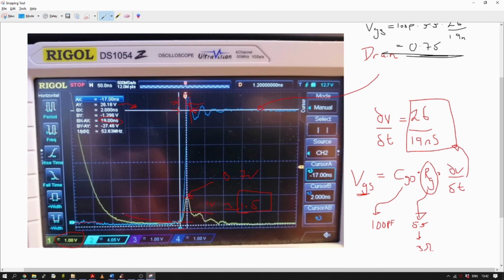things. You can see here that this is a turn-off curve. It's quite nice and smooth. There's no ringing, which is going to induce any nasty EMI. So I could probably drop it down a bit to 3 ohms, and that would drop this down sufficiently that I'm not turning on the FET. But as you can see, there isn't any evidence of shoot-through. If there was, you'd see this blue line doing some horrible stuff, and these FETs would be heating up considerably, but I'm not seeing any of that. But it is something that maybe I want to change.